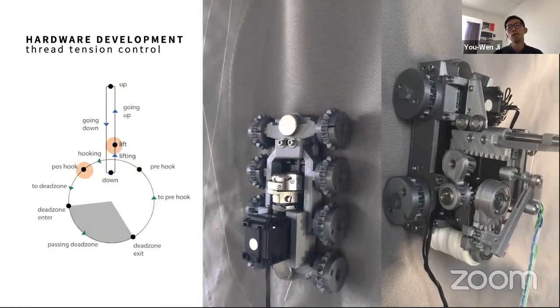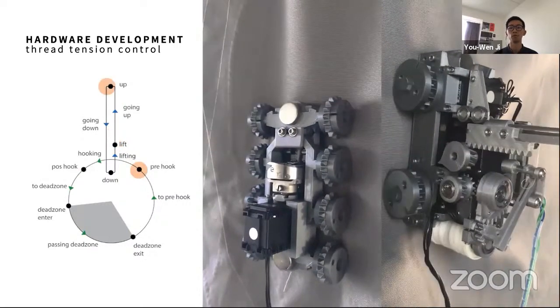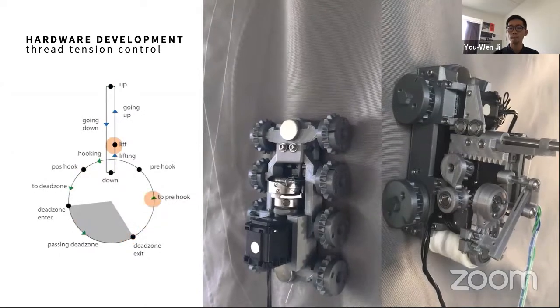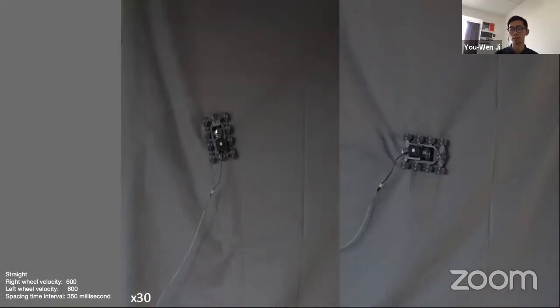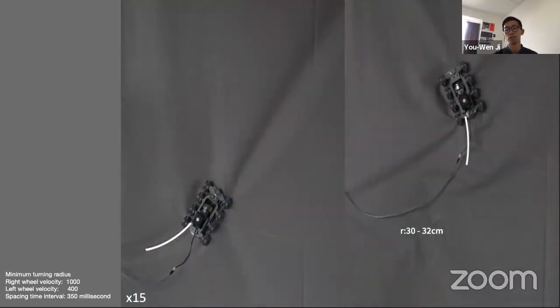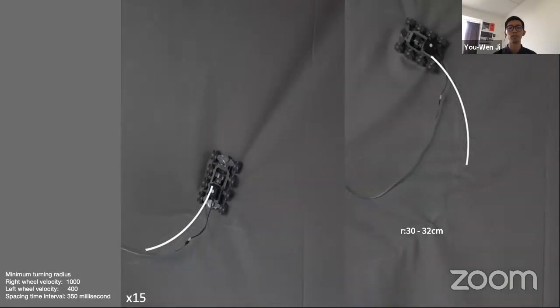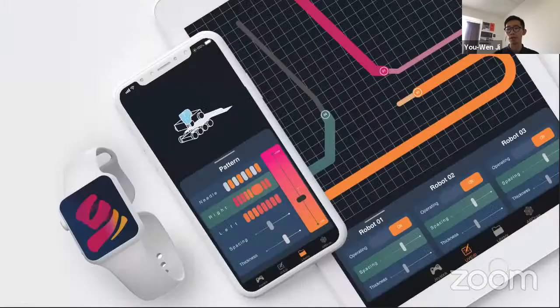In the sewing protocol, the motor position value was taken into account in every iteration of the control routine. To evaluate the needle breakage, the experiment evaluated the vertical surface with a curved seam using offline control. In this experiment, the robot could stitch vertically and horizontally, and also a circular seam, but it seems unable to keep the consistency of orientation and the stitching radius. So the semi-manual control from the designer in real time allowed adjusting the robot deviation as well as making design decisions on the fly.